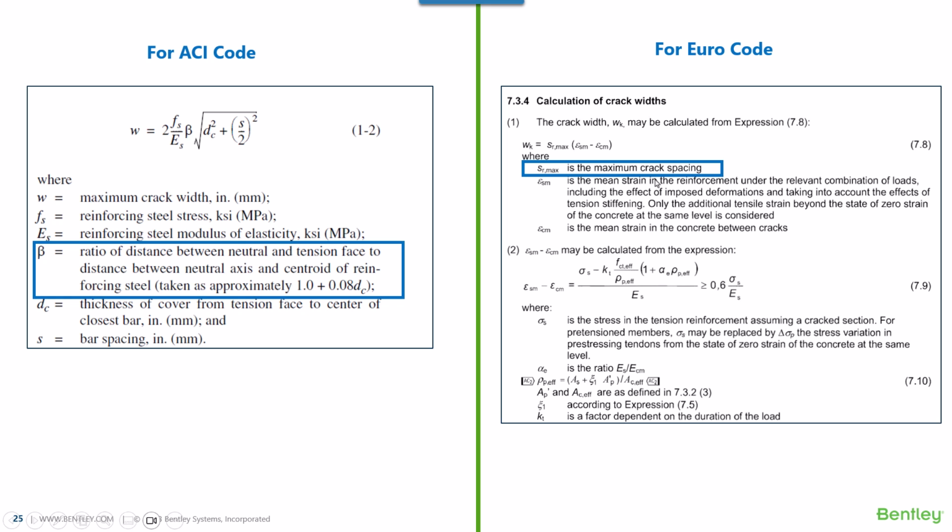Hence the value of P1 and P2 remains the same at any location, since the strain is also remaining the same. And for side face, the crack width would be less as strain will be less for the side face. So that is why the option for performing the crack width check at the corner or side face is not applicable for ACI code or Eurocode.